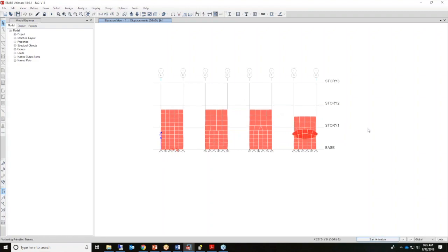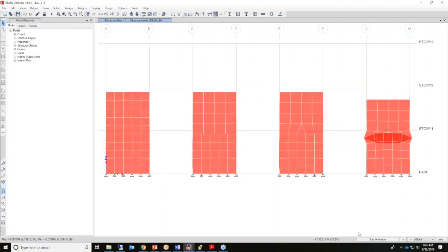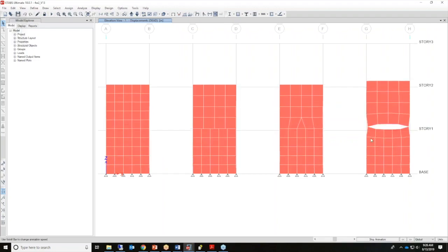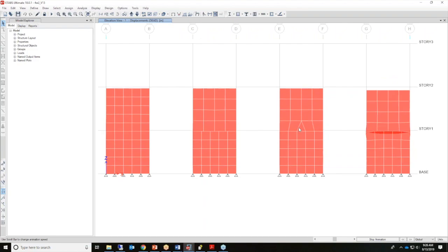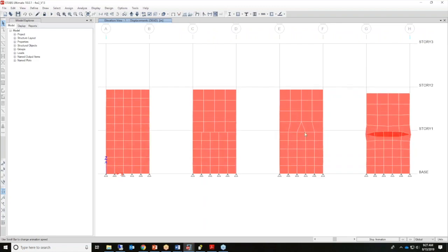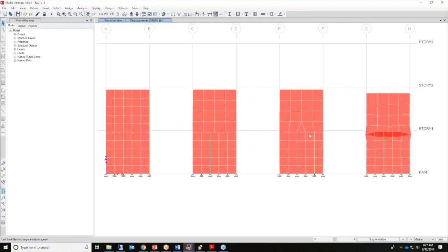Okay, I'm looking at the deformed shape. You can see here the edge constraint is working quite nicely in this second wall, creating connectivity. Obviously not the case for the fourth wall. Connectivity only remains at the edge. No connectivity has been shown here in the middle, as you can see very obviously. This third wall is a situation where I created some area objects that manually manipulated the connectivity between the nodes, which worked out fine. It takes a little bit extra time. That's why manual meshing does take a little more time than, of course, the automated internal meshing.